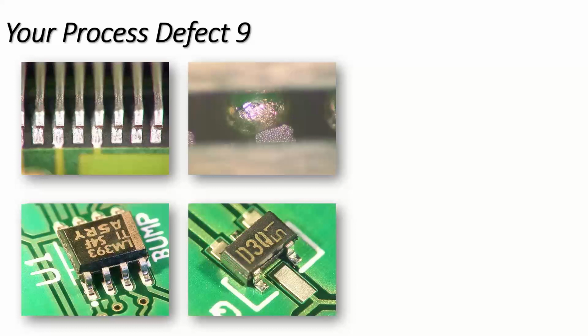Next question: what was the real cause for the solder crack in the plated through hole? Well, basically, it's fatigue. That particular solder joint was used in an application where it wasn't appropriate. Force was being applied to the component as part of the operation of the equipment, and that led to it.